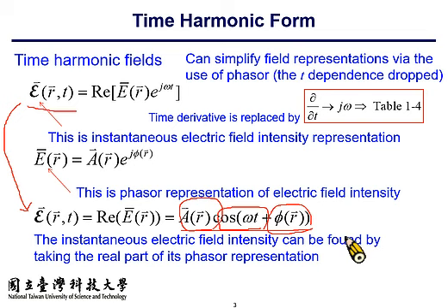In general, wireless communications fall into the group of narrowband. They use a narrowband carrier frequency, and you apply modulation, so you can couple the information you would like to transmit into the continuous wave, which is a sinusoidal signal. All right. So in most cases, the signal we are interested in is of a specific frequency,